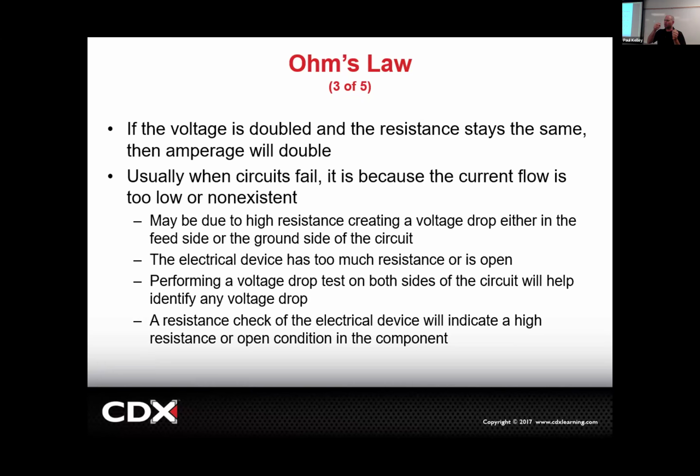And it's because those 3 strands of wire out of the big bundle of 50, you know, in one wire, there's all these multiple strands wound in there, right? So if there's supposed to be 50, that's enough to carry all the current and not add a voltage drop. But if you have only 3 and you use your meter with your little 9-volt battery, it's going to be like, yeah, this is good. The electrons can make it through there. Yeah, but you're only sending a little tiny bit. And they're like, everything's fine.